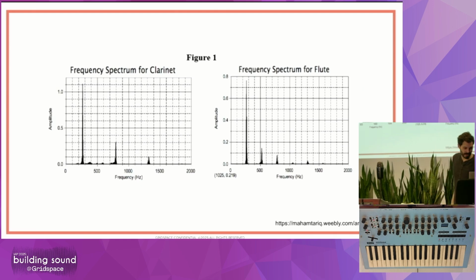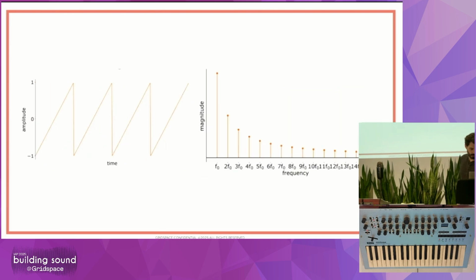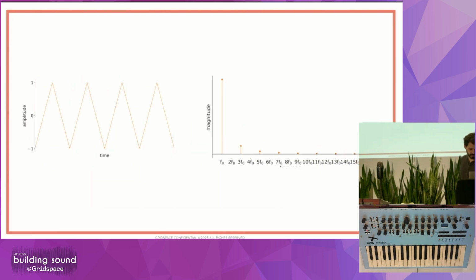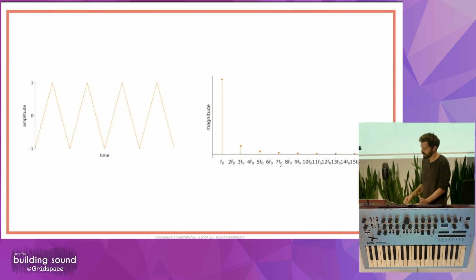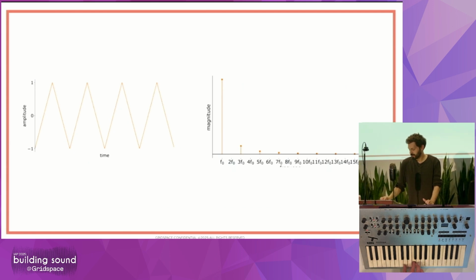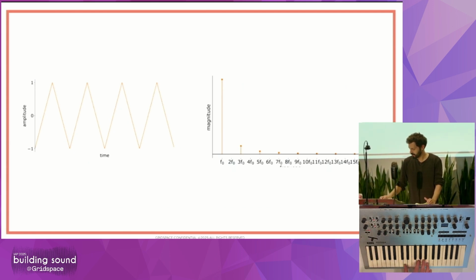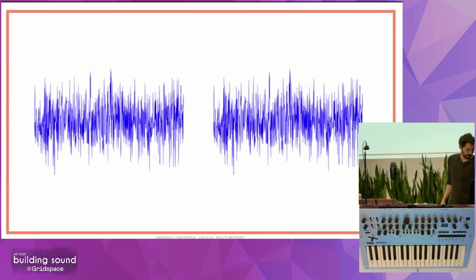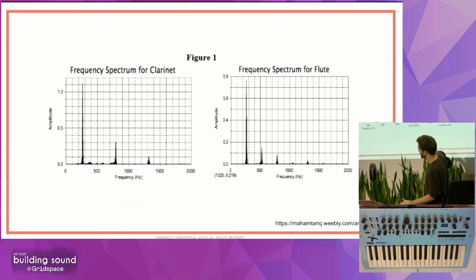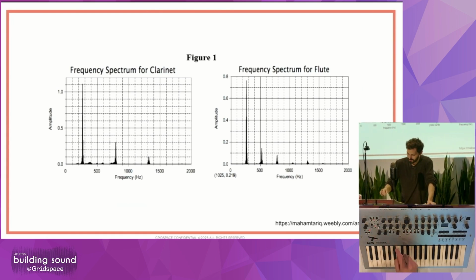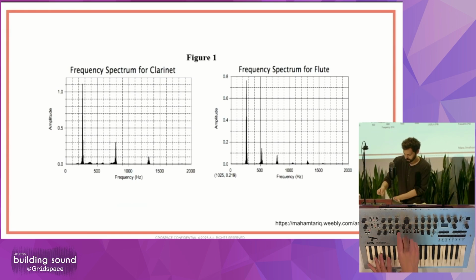So to me it looks like the triangle wave. And so if you were wanting to reproduce a flute sound, you might start with a triangle wave. And already that's a little bit flute-like, but we could further refine that by saying we want actually some of the even harmonics too. So what if we just added in a square wave as well, but at a lower volume.